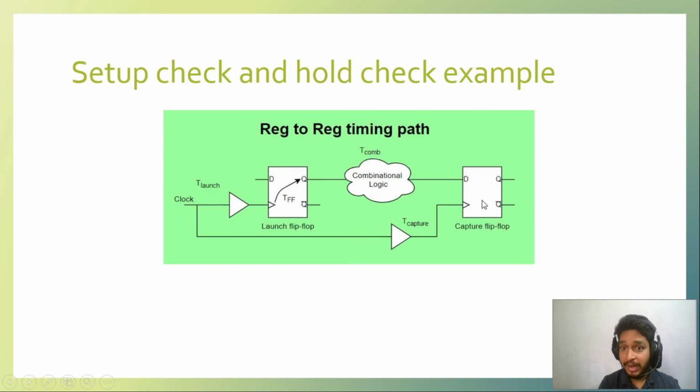So from this D pin to the output of the second inverter, where there is a pass transistor. So it has to reach from here to that output of the inverter. From here to here, that is the setup time. So the total time from this Q output to this output of the inverter is 1 clock cycle. So what is the time available to reach this D input? That is actually the 1 clock cycle minus this setup time, right? That is the actual equation that we have.